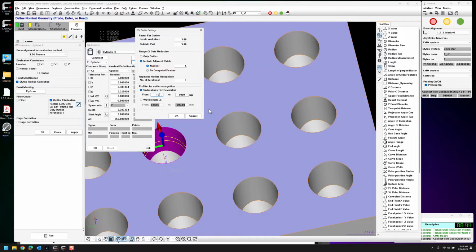And now we're going to do our pre-filter. Of course, because it's the first box here, we're going to put the number 10 in the first box. Again, real easy to remember. If I'm using the first radio button, I put a 10 in the first pull down field. If I'm using the second radio button, I put the 10 in the second field. The first one is for rotational, revolution. The second one is wavelength, linear objects. Easy to remember. Always use 5, always use adjacent, always stay with plus or minus 3 standard deviations, except in special cases.